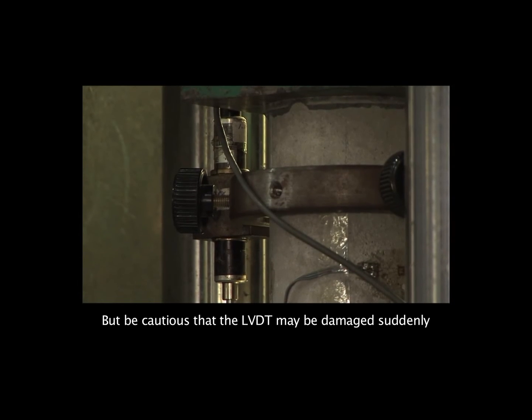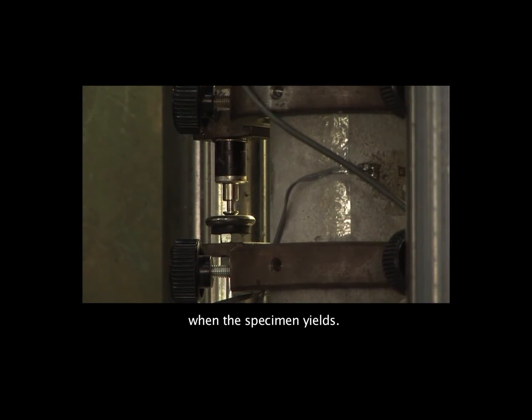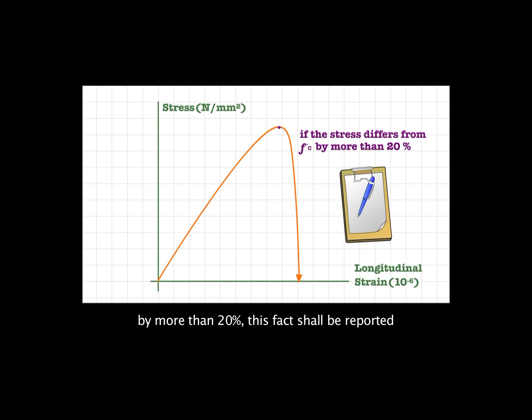But be cautious that the LVDT may be damaged suddenly when the specimen yields. Also, if the peak of the stress differs from Fc of companion specimen by more than 20%, this fact shall be reported.